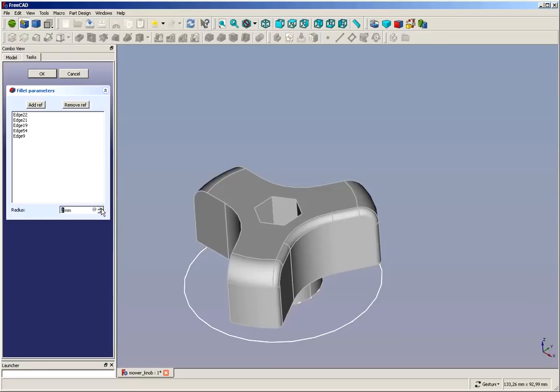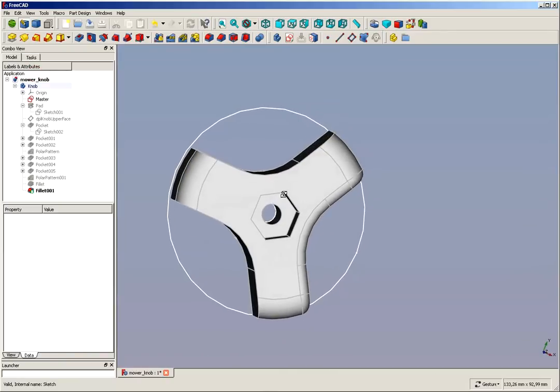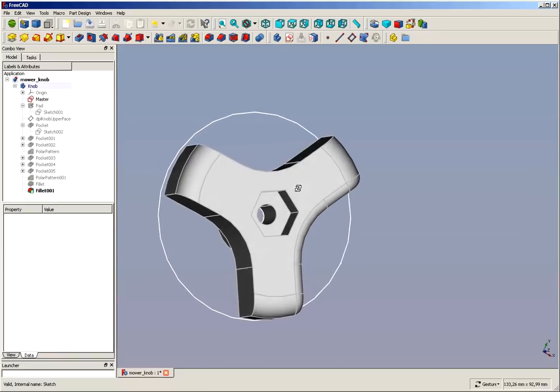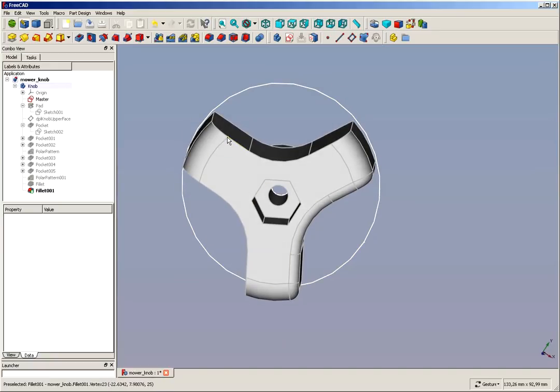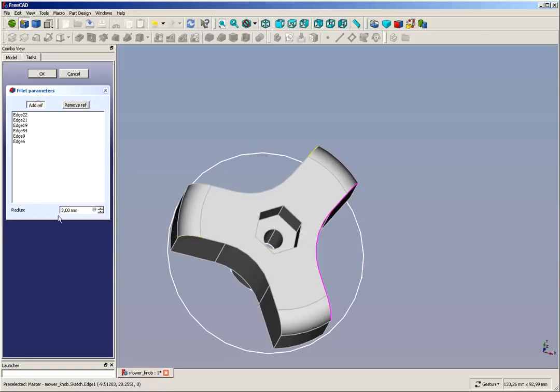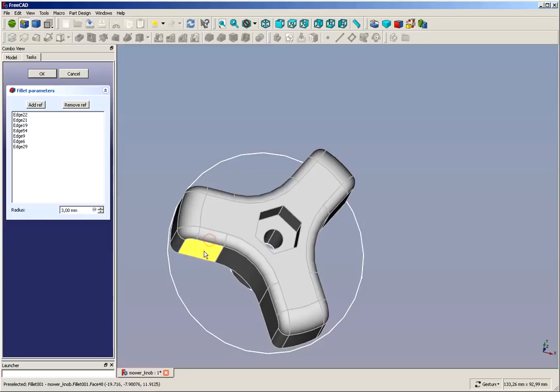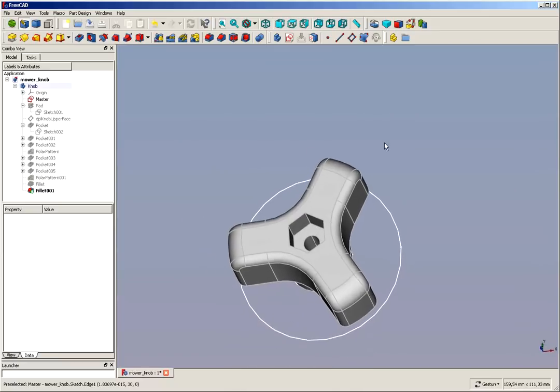When you're doing fillets, be sure to create them in the proper sequence. Sometimes if you're doing fillets in the wrong sequence, it won't work. It will create impossible geometry. Do this. So we want to add more references. Add reference. That one. Pretty nice. So that looks fine.